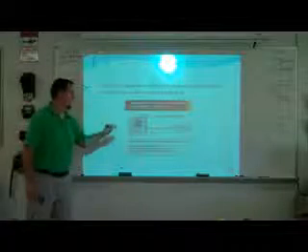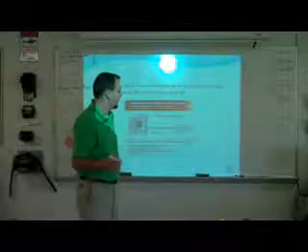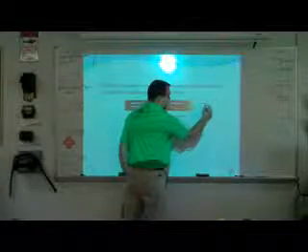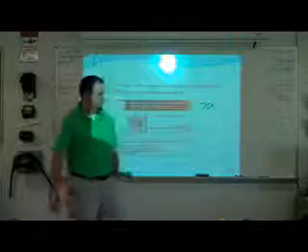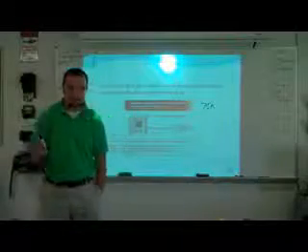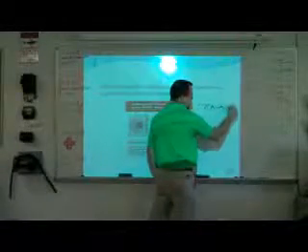OCPDs, which stands for what? Overcurrent protection device of 800 amps or less, which do not correspond to a standard size, I'll round it up. So let's say we go through here, and we're going to do some of these later, but we figure out that we need 75 amps of protection. You're not going to round down, right? Our load comes up to 75 amps. That isn't an actual circuit breaker size, so we supply it with an 80 amp breaker. Okay, that's what that's saying.